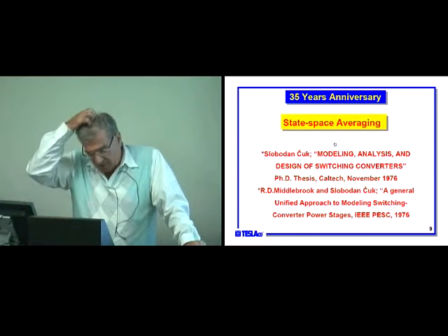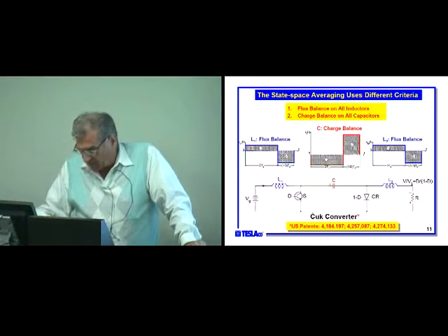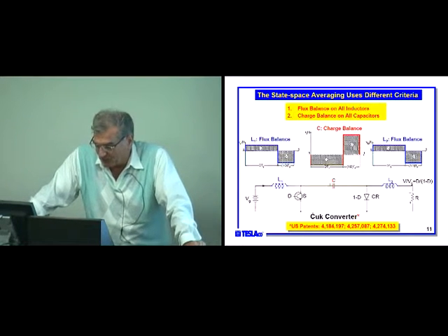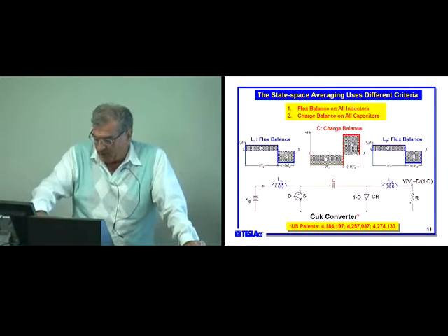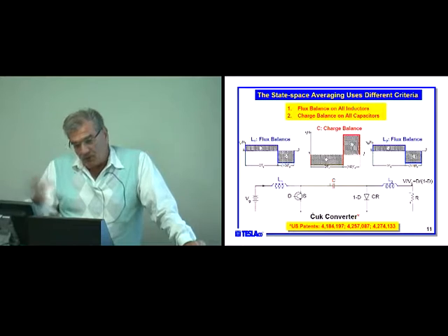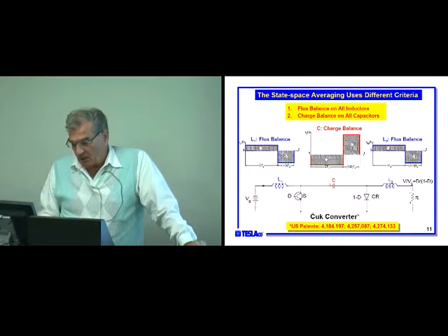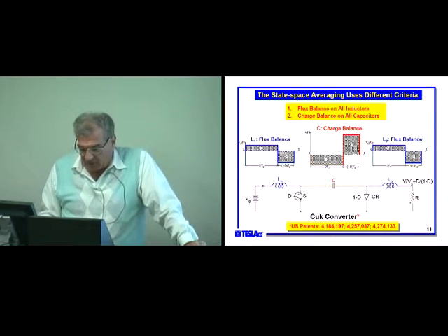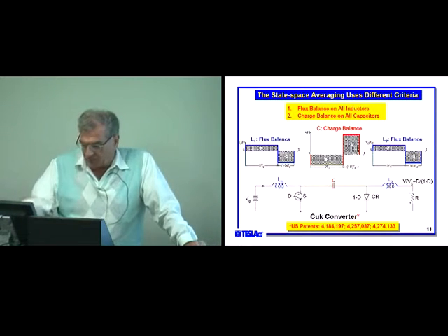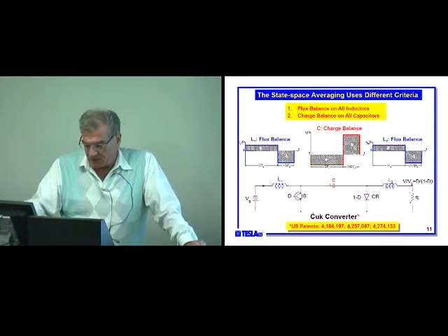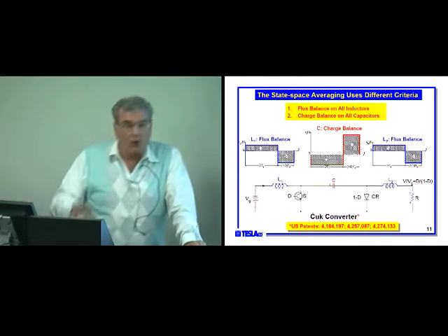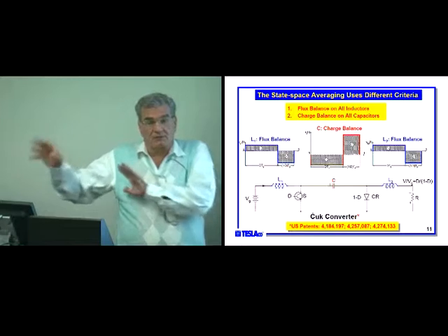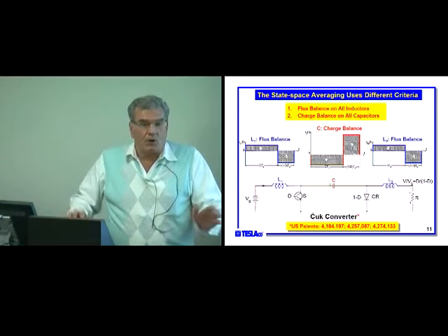Here, in the process of that, I invented what's called the Cuk converter. You can go to a web page and find 90,000 references to it in books, etc. But anyway, the key to that was a new type of converter, one of the 4 basic converters, which I actually used as a vehicle to develop this method, because it had a capacitive energy transfer. You see this one in red. In addition to all the conversion methods up to now, which used switches, inductors, and transformers, for some reason, they ignored capacitors.